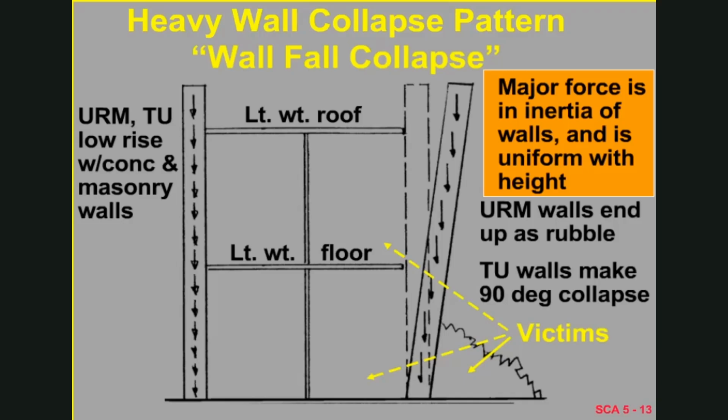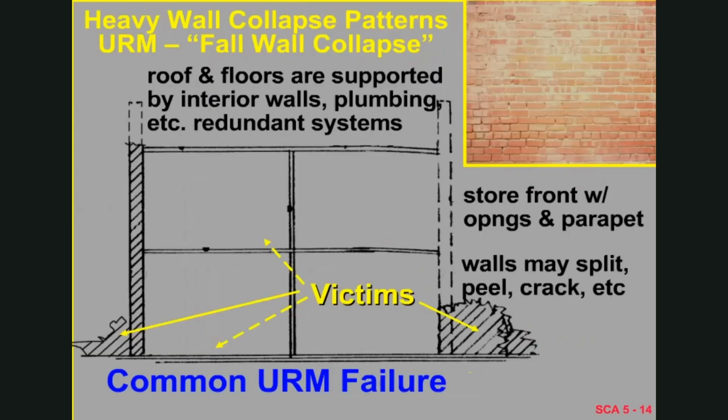And the earthquake slogan of duck, cover, and hold was developed for just this kind of building, where you don't want to run outside as it's collapsing, because you would get in the way of the collapsing wall. The spaces inside the building often are formed for survivable voids, and so that's where you would find some victims inside the building in whatever voids are left, and you could also find them, although mostly dead victims, outside underneath the walls. Another picture of the collapse.